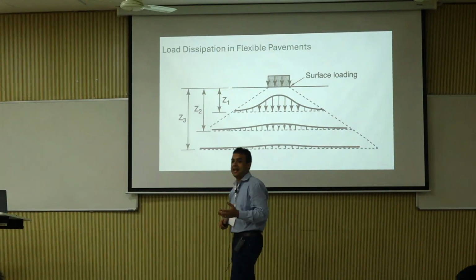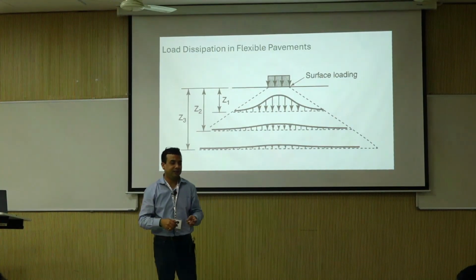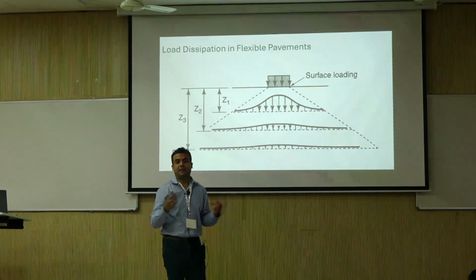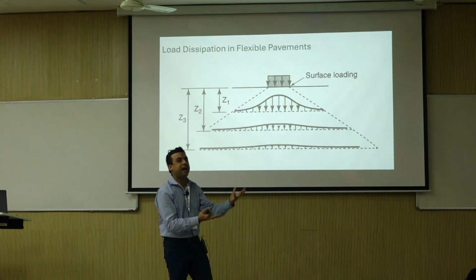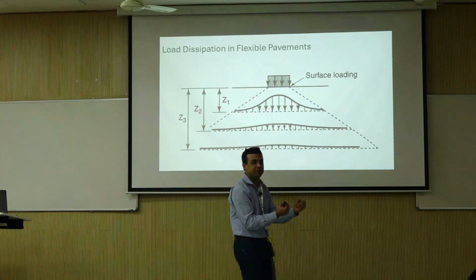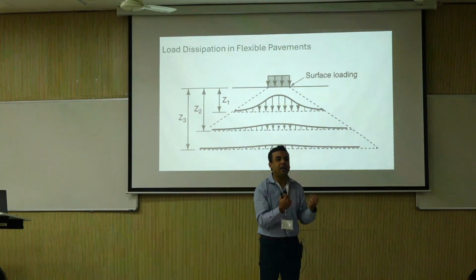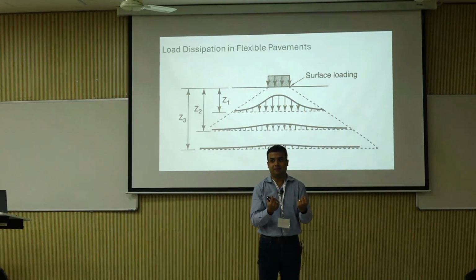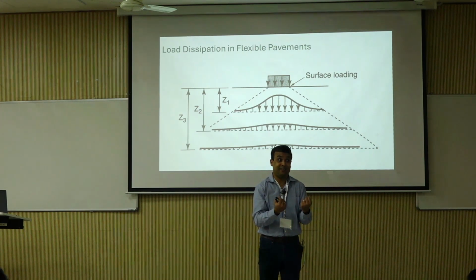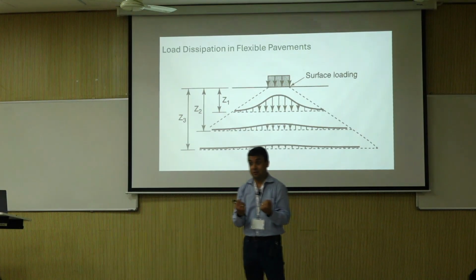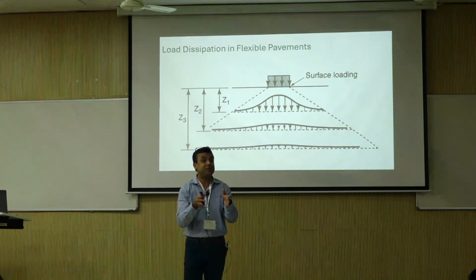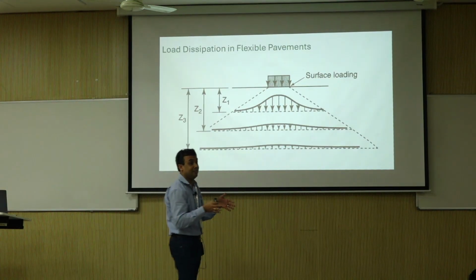Similarly, we will get to this on day 3. People say things like, I have a very high resilient modulus, or I have a very high modulus, so this is a very strong layer, right? No, it's not. It may be a stiff layer, right? Strong represents strength. Modulus has nothing to do with strength, right? So pay attention to mechanics, pay attention to physics, right?